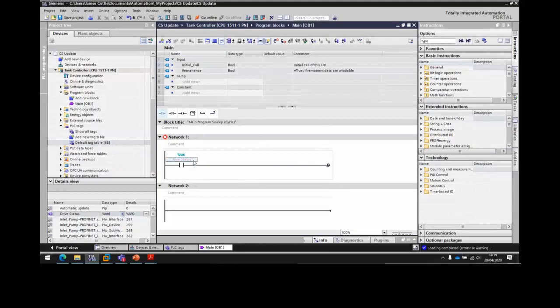But if I want to just get a bit within this, slice access allows me to do that simply by pressing dot after the tag name, and then doing something like x0 allows me to access the first bit, or bit 0, within that word. And we could do this for any bit within here, so we could do x9 as an example to get at the 9th or the 10th bit, depends how you look at it, within this particular word.